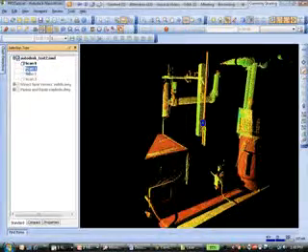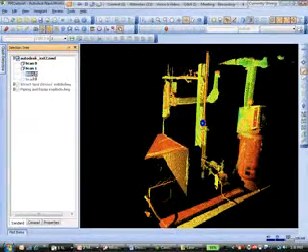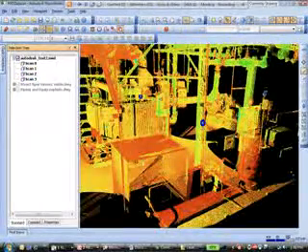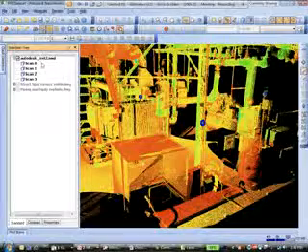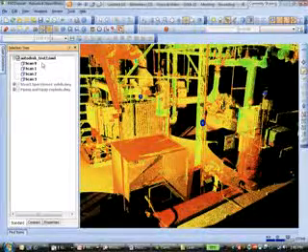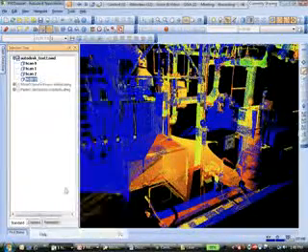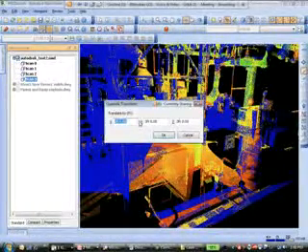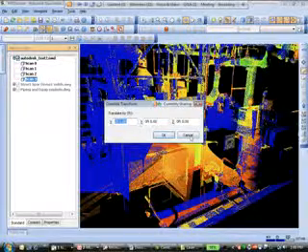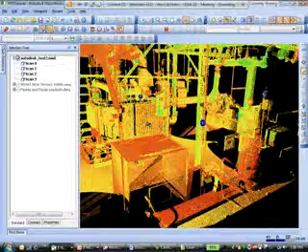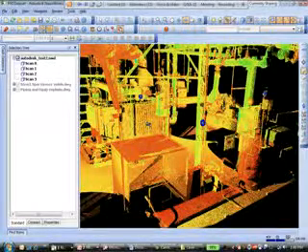But typically it's the scanning software that's going to be bringing these different elements in and positioning them. However, we can still bring in multiple elements, and inside of Navisworks, position them around. I can come in and select one of these elements, and either in the override transform, I can move it around on screen, or we can use some of the other tools to snap them into place. It becomes a little more challenging though, because you may not have a clean edge. It may be hard to set where one scan starts and one ends. But typically your scanning software will encompass that.